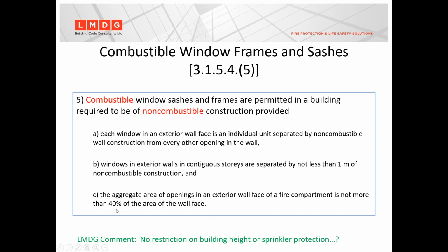Before I go into the couple of problems with these rather antiquated limits, let's define what are combustible windows in terms of how the building code is practiced. So combustible windows consist of windows where their frames are made from fiberglass, other composites, or PVC or wood, which leaves non-combustible as an assumption for aluminum windows, even thermally broken aluminum windows. So whether the science backs that up or not, we'll get there in a minute. That is how the code is applied in Canada.